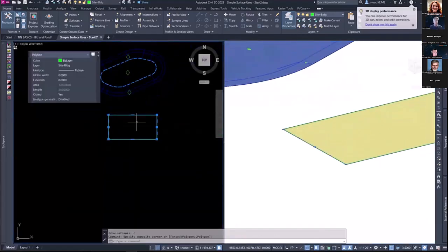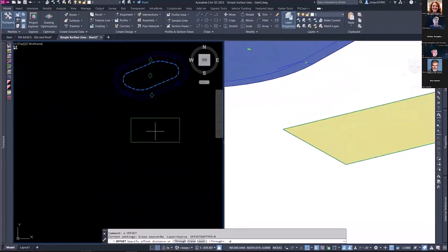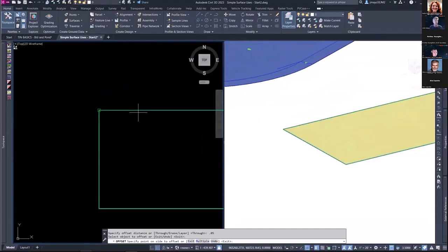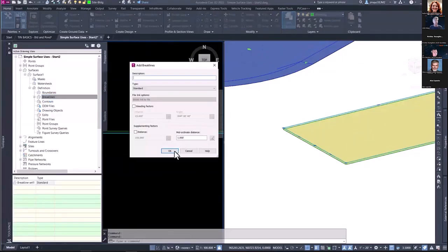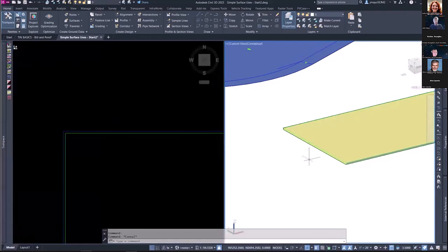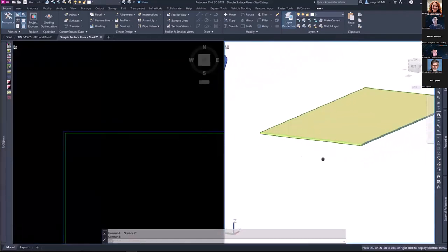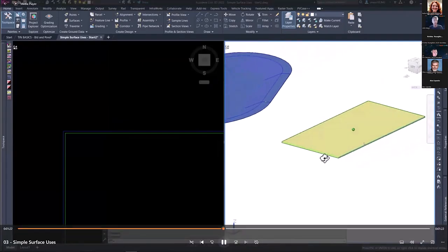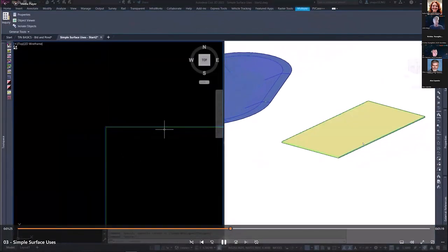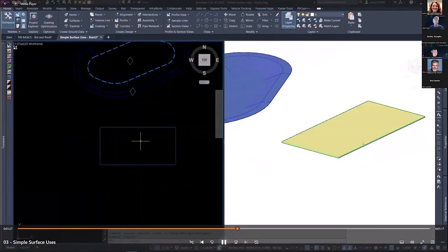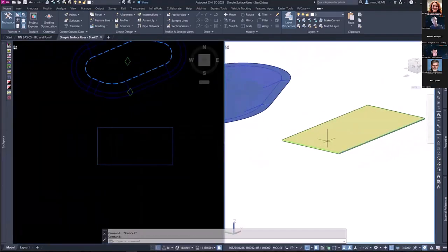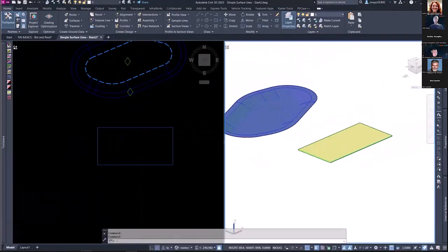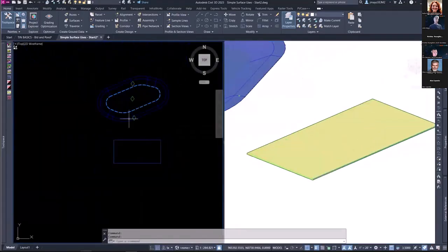And it's nothing major, it's the polyline. So I offset that 0.05 units, and I'm going to do that because I am going to raise this a half a foot and add it to the surface as a break line. And that plane, well, now it's an equipment pad, a concrete pad, you know, a gravel pad if I send it down. And it's just a couple of polylines, and it takes seconds to create. That's the big idea to get across here. The surfaces are very stable, simple to create, and don't always need to be an existing or proposed ground topo.